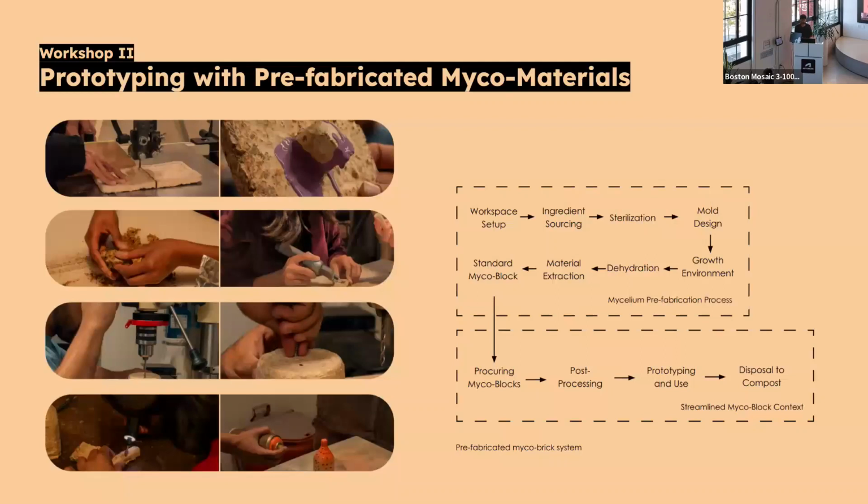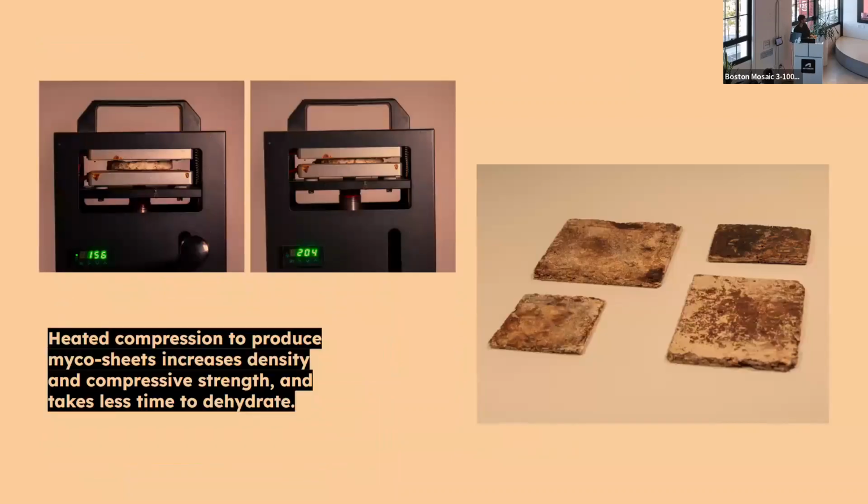Inserts and drilling works, but I think that it could be better because the material is slightly soft because of its composition, and the mycelium is generally not grown throughout the material. So the outer surface is usually harder than the inner part, which is usually a bit softer and crumbles a little bit more easily. So there were still some limitations in these blocks. One of the processes that we tried, I got this idea from Andreas Mershon, who's leading the BioHab project at MIT, and he suggested that we should maybe try compressing these materials, and that worked really well.